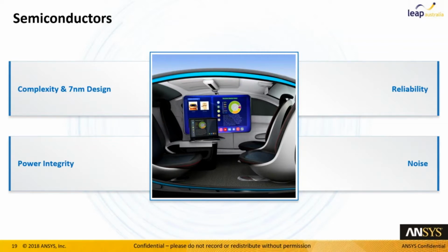One important point is the reliability on that. I would just like to mention two aspects. The first is electromigration, where we have movement of metal ions that create voids and also hillocks in traces in wires. We can do a full chip analysis on those applications, and then test it based on current direction, also on temperature, and make a call on where we have electromigration on our chip.